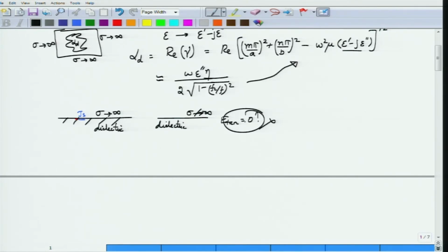This condition is true only as long as the conductivity was finite. Now we are trying to calculate the losses where the conductance is not finite, for which I cannot use the original boundary condition. Now I seem to have two options, or at least one option immediately, which is to write Maxwell's equations for lossy conductors, and re-obtain all those expressions for TE and TM modes.